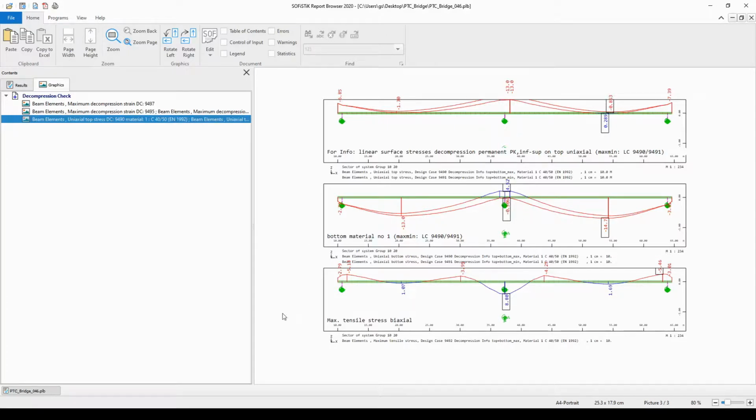Both the top and the middle picture were calculated based on uniaxial loading. Now let me talk a little bit about the bottom picture. This picture presents the maximum tensile stress in the concrete from a biaxial loading, and one should think at first blink that basically this diagram presents the maximum value of the top two diagrams.